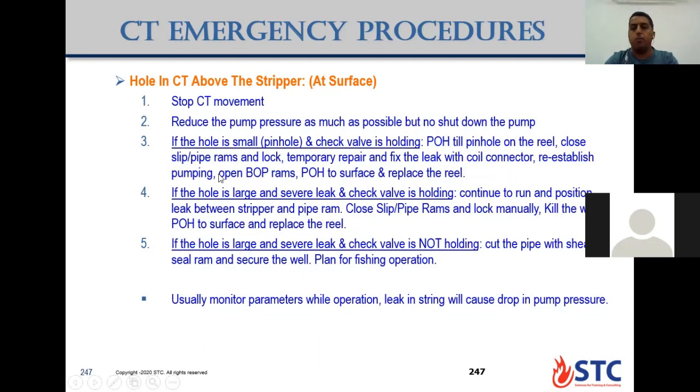Usually, from time to time, we need to make a full inspection of the coil tubing to detect any defects, so you will not have any problem like a pinhole or crack during the operation. And usually monitor the parameters during operation, because if you have a leak in the string, you will have a drop in the pump pressure during the operation.